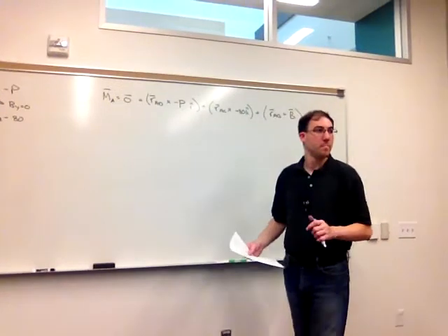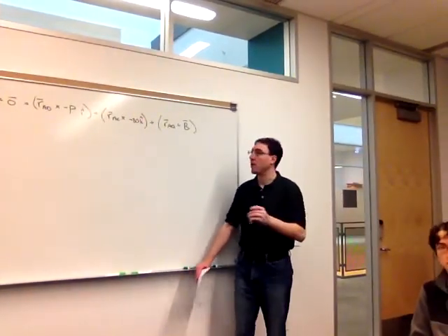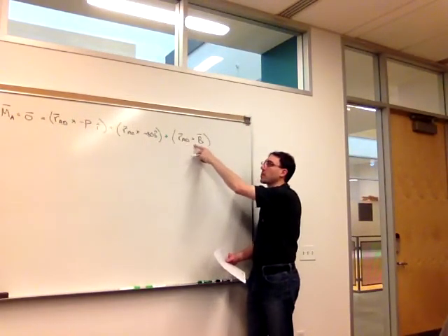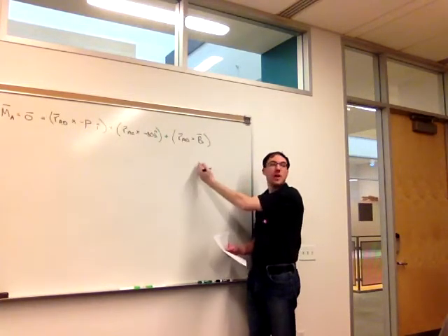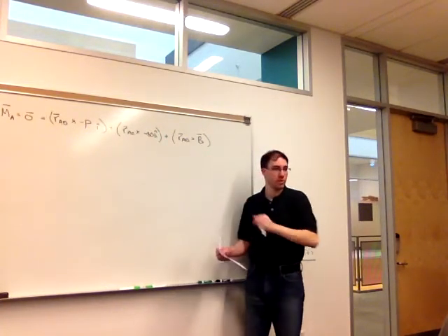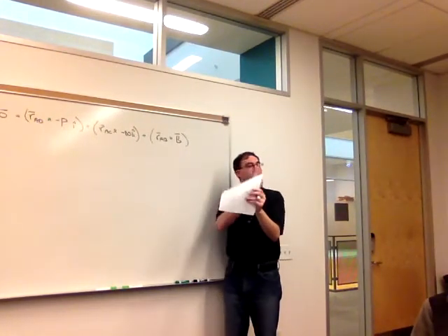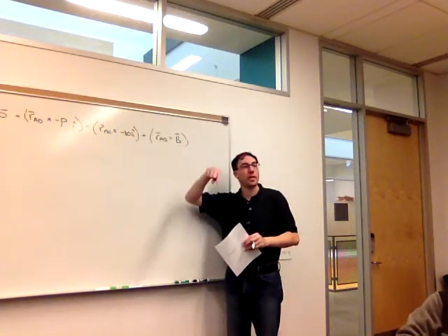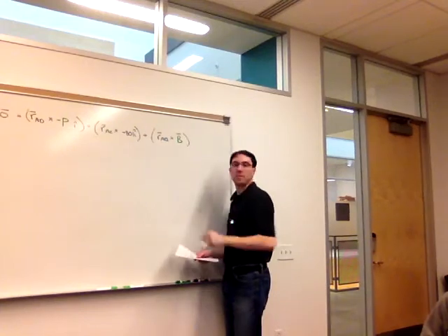Would that be similar to the test question where you could sum the vectors at that point? Right, exactly. Since there were multiple forces at that point, RAB cross this, plus RAB cross that, plus RAB cross this, we can factor out that RAB and just add those 3 forces together. So the same as in the test, you could add all the forces together and then take the components. This one's easier because each one only has an I, a J, or a K component. So it's just a little bit simpler to do it this way.